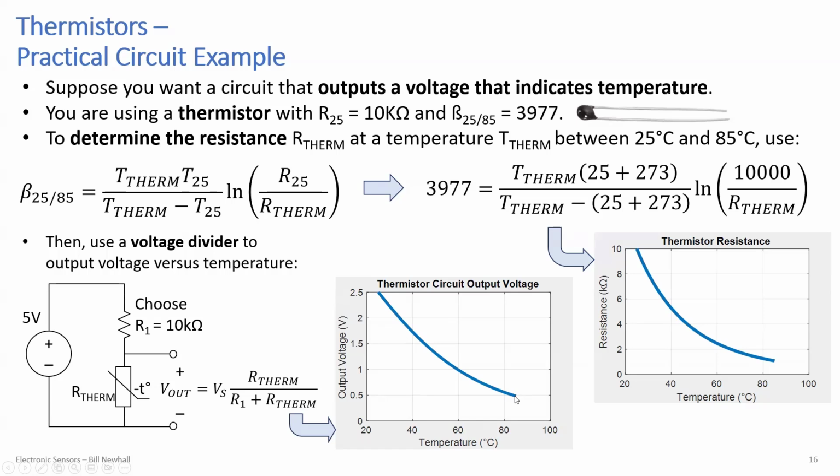You could set up your Arduino in lab to measure voltages. You're using a 1.1 volt full scale range. You could change that to be somewhere in the mid 2s or even 5 volts and still get a reasonable measurement here. But you could sample the voltage and then do a conversion, maybe even just by table lookup between voltage and temperature, and you could calculate the temperature.